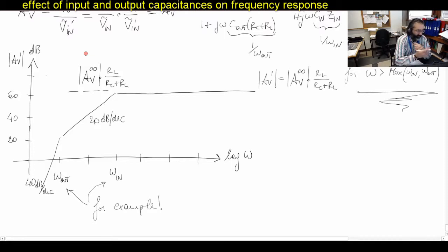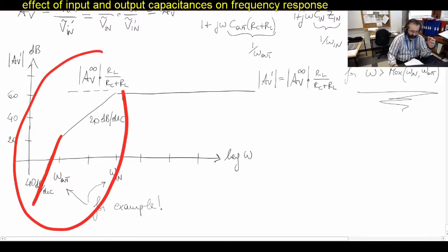But below those frequencies, we should expect that when omega in kicks in, there is a 20 dB per decade effect due to the first filter kicking in. If also the other filter kicks in, then there is an additional 20 dB per decade, and so this will go as 40 dB per decade now. And so we can clearly see here a high pass filter behavior.